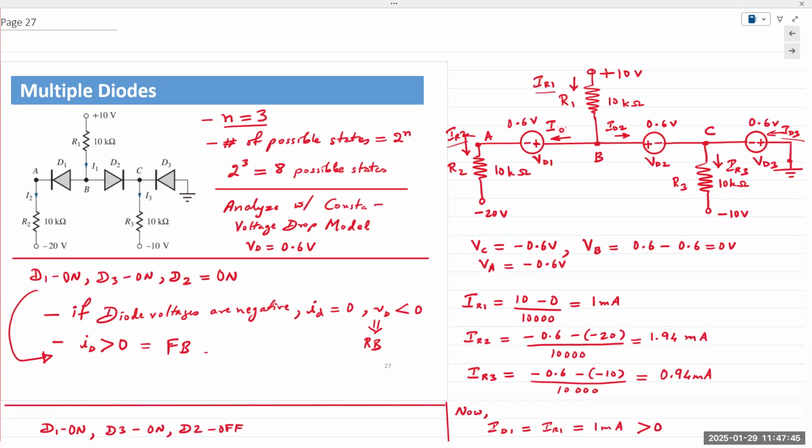Okay. And I'm just going through the logical steps of circuit analysis. So I first make an assumption, then I replace the diodes based on those assumptions. Then again, based on those assumptions, I'm going to outline the diode voltage polarity and the diode current directions, right? So if you take a look at ID1, ID1 is the same current that's flowing through R2. So ID1 is the same as IR2 in series. So if I find IR2, I get ID1.